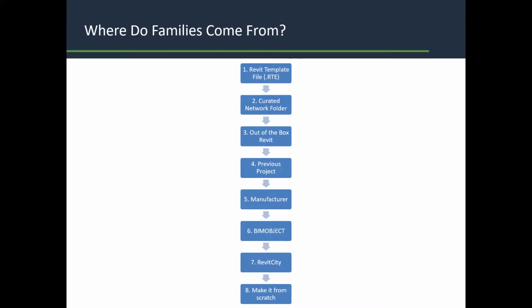They have 1.2 million members and 20,000 plus parametric BIM objects available free to download. And they have a misleading rating system that simply reports number of stars and number of downloads. So I advise people to never download content from Revit City directly into their project. I would at least use a proxy project first, or better yet, test and flex each parameter of the object before utilizing it in your project.